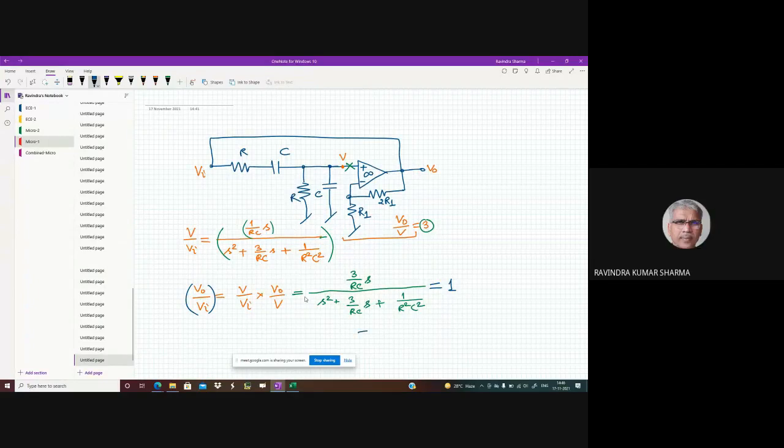Yes, sir. अब जरा इस पूरे को देखो। This is now equal to 1. साइनोसॉइडल वाली बन जाएगी सर। तो अब क्या हो जाएगा? इसका जो कैरेक्टरिस्टिक इक्वेशन है, कैरेक्टरिस्टिक इक्वेशन हो जाएगा S स्क्वायर प्लस 1 over R square C square equal to 0. ठीक है, तो इससे ओमेगा नॉट या ओमेगा एन क्या मिलेगा,